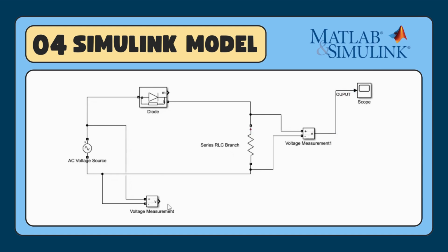Next, the voltage measurement block. This block is used to sense the input and output voltages. These signals are sent to the scope for waveform observation. Lastly, we have the scope block. This block displays the waveform. One channel shows the input AC waveform and the other shows the rectified output waveform. This allows us to visually compare the theory with simulation.